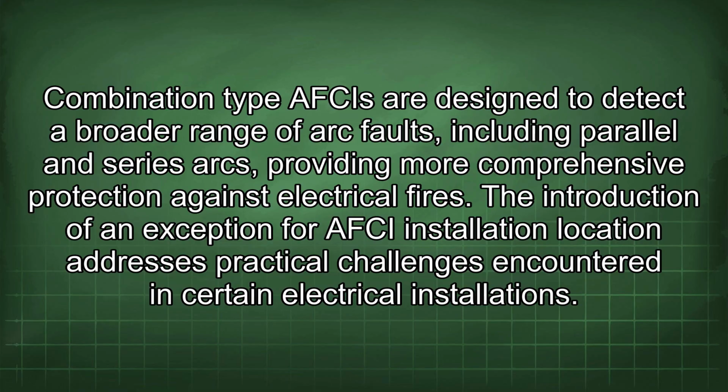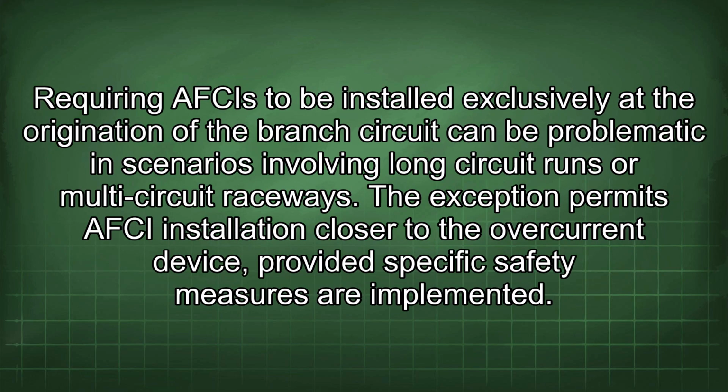The introduction of an exception for AFCI installation location addresses practical challenges encountered in certain electrical installations. Requiring AFCIs to be installed exclusively at the origination of the branch circuit can be problematic in scenarios involving long circuit runs or multi-circuit raceways.